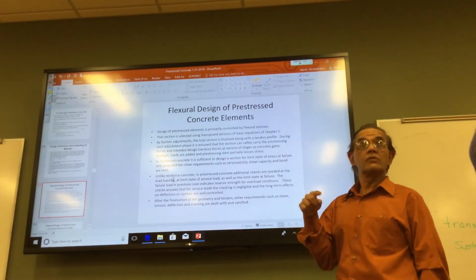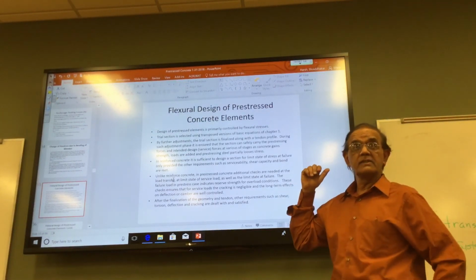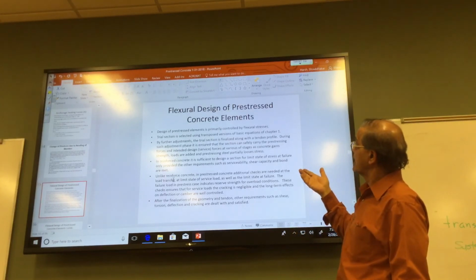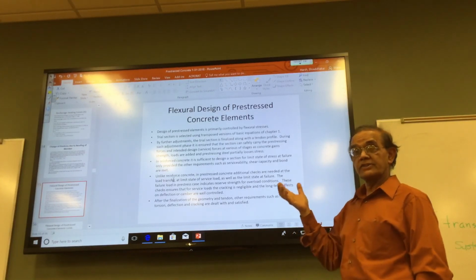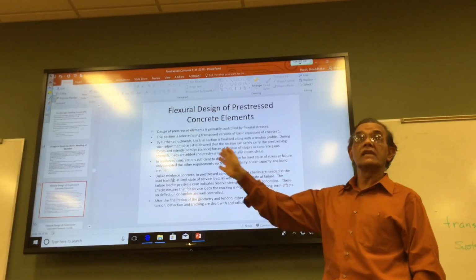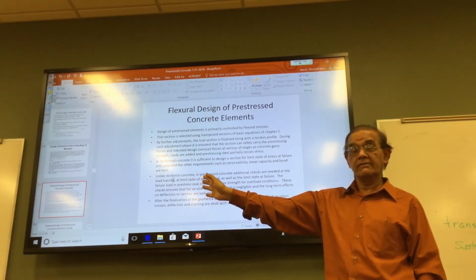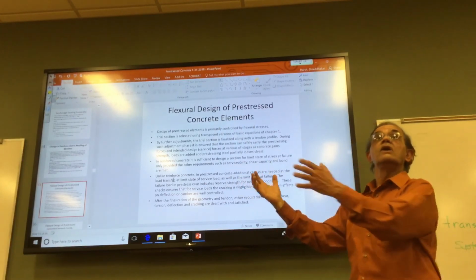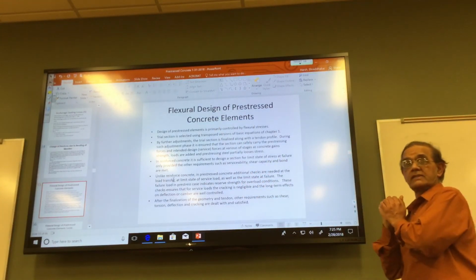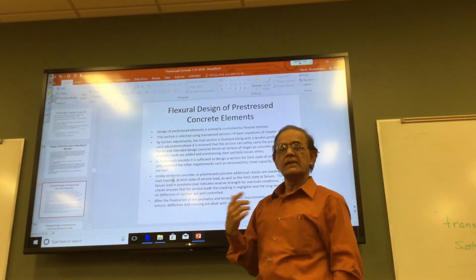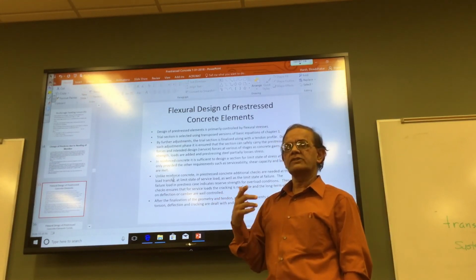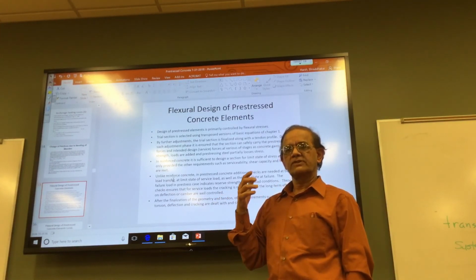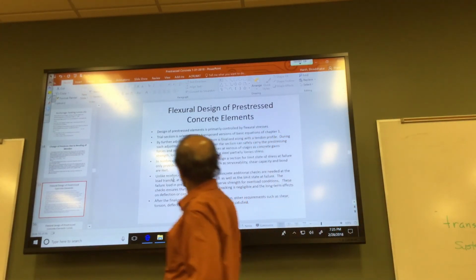So there is a section modulus in there on the right-hand side. If you transpose the equations, then the section modulus can be brought into the left side where the stresses FT or FB are. You can have ST or SB and then all the other stuff on the right-hand side. That's the general idea. And then you do it such that your stresses, now here's the difference, and we will talk more about that.